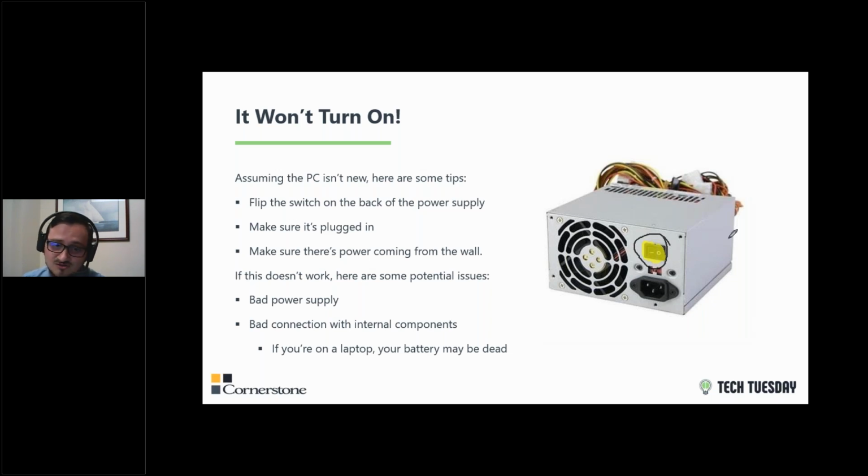So 9 times out of 10, you just need to replace it. If you are particularly interested in doing so, this isn't something that I think a professional needs to do. All you need to do is open up the side of your computer case, unscrew your power supply, unplug all of that mess of cables that I have particularly thrown away back here, get a new one, plug them in exactly where they were before with the exact same looking plugs, and then screw it back on, put your case back on, plug it all in, and power it up and see if it works.